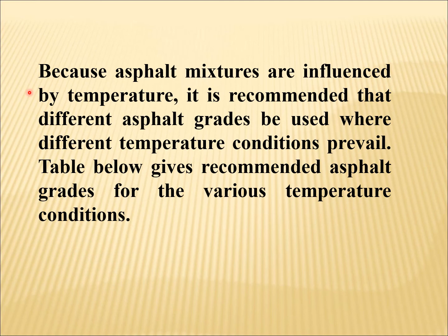It would become soft. Because asphalt mixtures are influenced by temperature, it is recommended that different asphalt grades be used where different temperature conditions prevail. The table on the next slide gives recommended asphalt grades for the various temperature conditions.